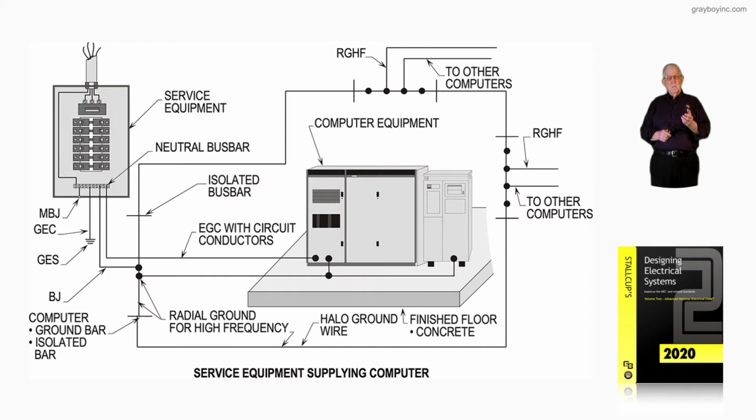Now if it happens to be any kind of agricultural type settings, then 547.2 and 547.10 deal with an equal potential plane. It's defined in 547.2, but how to build one is in 547.10.